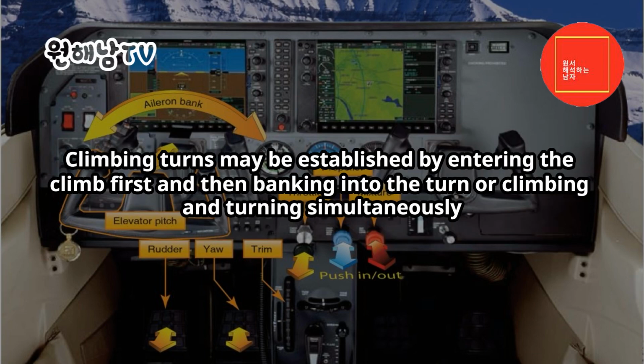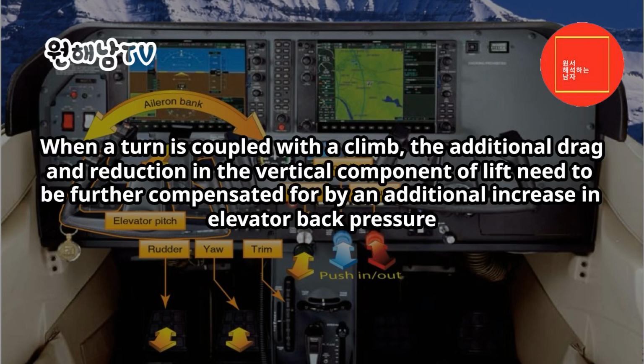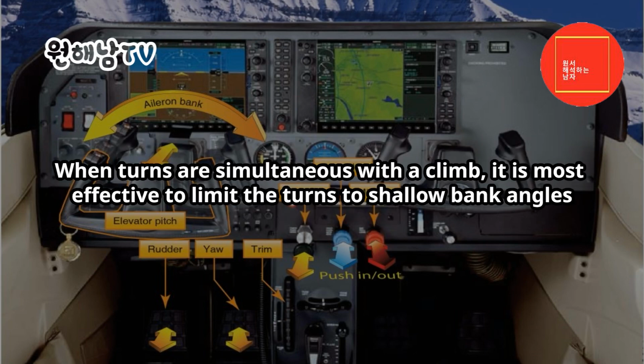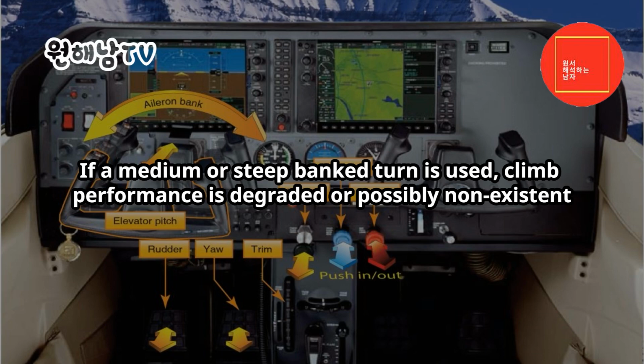Climbing turns may be established by entering the climb first, and then banking into the turn, or climbing and turning simultaneously. During climbing turns, as in any turn, the loss of vertical lift should be compensated by an increase in pitch attitude. When a turn is coupled with a climb, the additional drag and reduction in the vertical component of lift need to be further compensated for by an additional increase in elevator back pressure. When turns are simultaneous with a climb, it is most effective to limit the turns to shallow bank angles. This provides for an efficient rate of climb. If a medium or steep bank turn is used, climb performance is degraded or possibly non-existent.